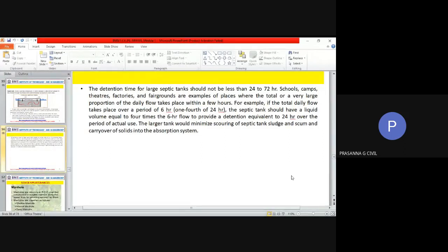So a repeat once again, the purpose of low cost treatment is, one, when you don't want to give any other associated treatment to your wastewater. So you are not having any industrial sewage, nothing is getting mixed. Okay, only say municipal wastewater which you want to treat in one step, either in a septic tank or in an oxidation pond. The cost wise, there is less in terms of construction.